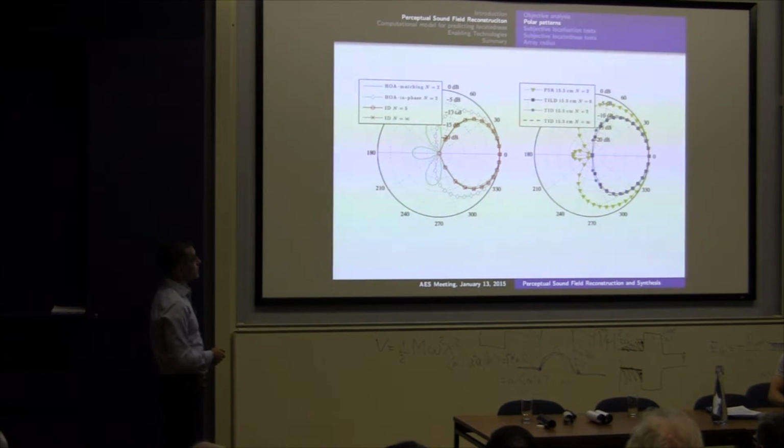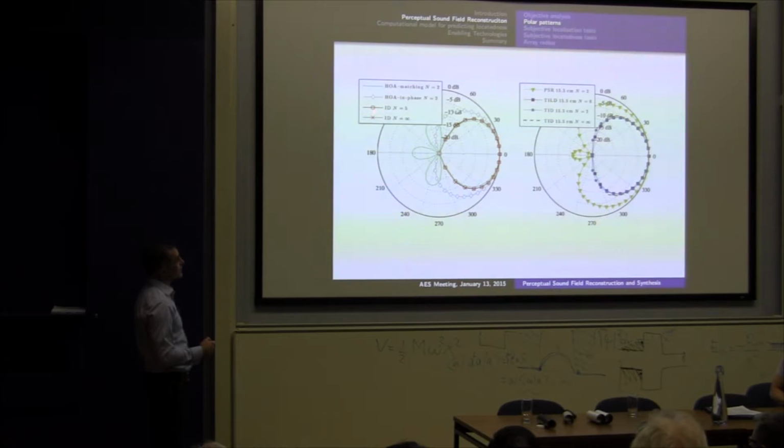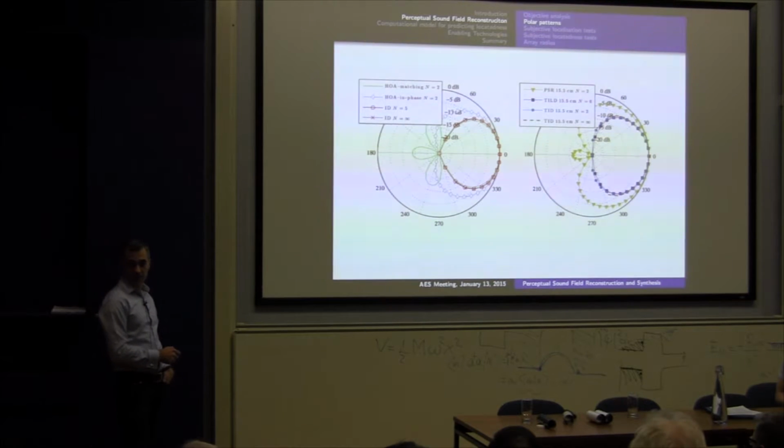Here we are showing some examples, comparisons of polar patterns, for instance, for second-order ambisonics with mode matching, which is the green line, and second-order ambisonics with in-phase decoding. Then we are showing the curve which would be obtained with 5 channels for the tangent panning law, which means just intensity stereophony. We can see that this tangent panning law intensity stereophony requires very, very selective curves.